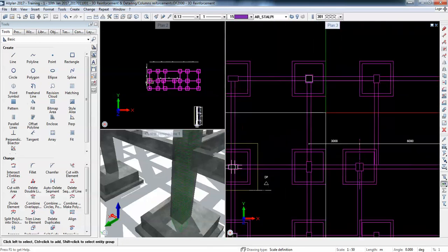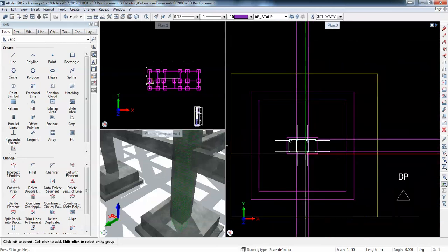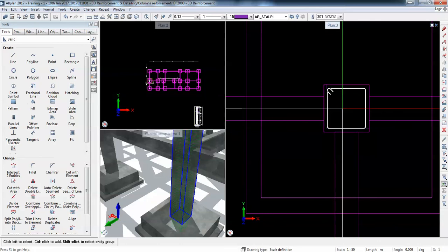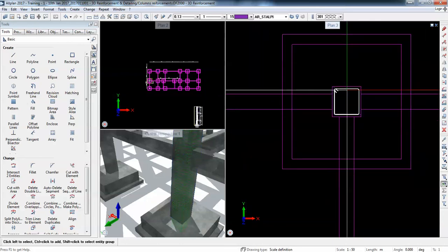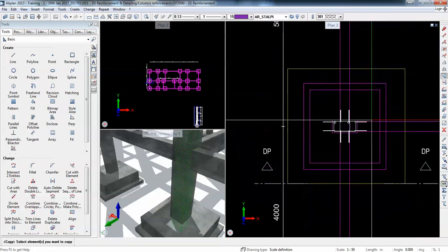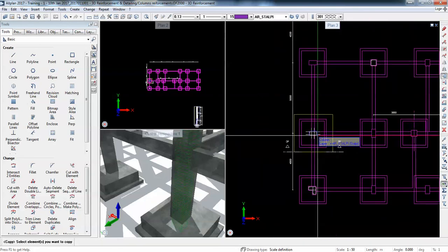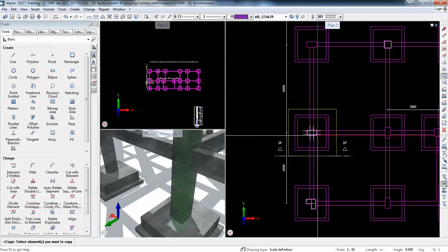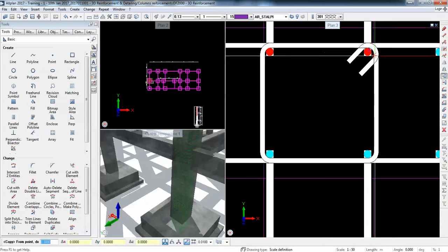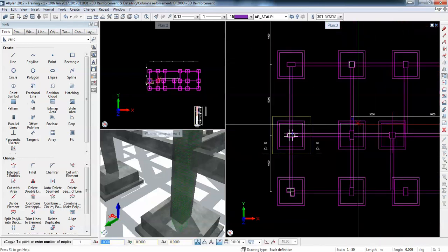So how fast have you reduced from rectangular to bigger rectangular to smaller rectangular? Well, I could have used also the bars. It's quite fast. Actually, what I do is when I'm first doing the formwork for a project, I identify which columns are the same as reinforcement, and to know how many types of carcasses I have to use. The adaptation is quite fast, and I'll show you by creating another reinforcement for this column based on the first one.